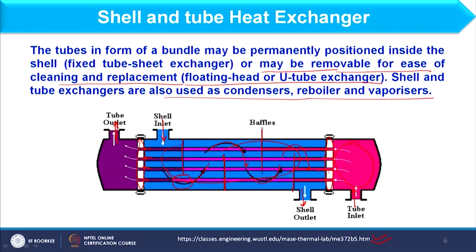Okay. So, when I am considering the tube bundle, it basically includes this tube sheet, these tubes, baffles and rods. So, where the rod is attached like this here. Okay. This rod is not part of the tube. Okay. And how this rod looks, it is like you must have seen TMT bars. Okay. So, this rod is like a TMT bar, where spacers are provided.